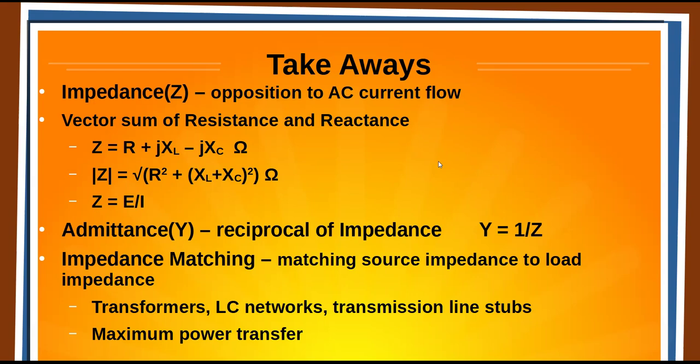You could do that, but because it's only a 2-to-1, it's hard to do it with a transformer. You probably need a pi or T circuit. If you're doing something like an end-fed or an off-center fed where you're matching a very high impedance, then you can do it with the transformer. Either 49-to-1 or 64-to-1.